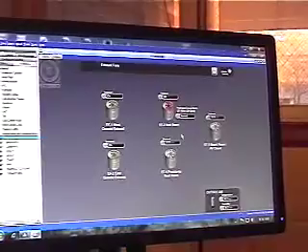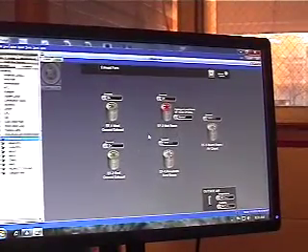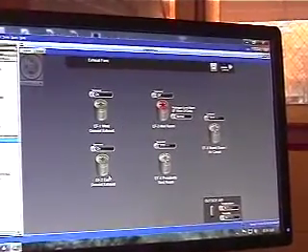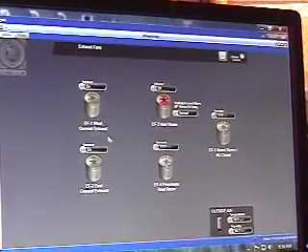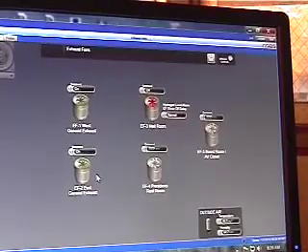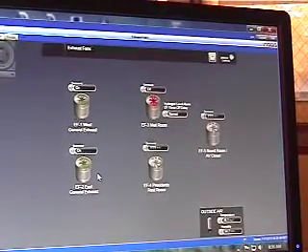Okay. So here's a link to all your exhaust fans right here. The biggest ones you're going to have are an east and a west exhaust fan, 1 and 2. These exhaust fans will basically just be on a schedule, so whenever the building's occupied, they run. If the building's unoccupied, they shut down.